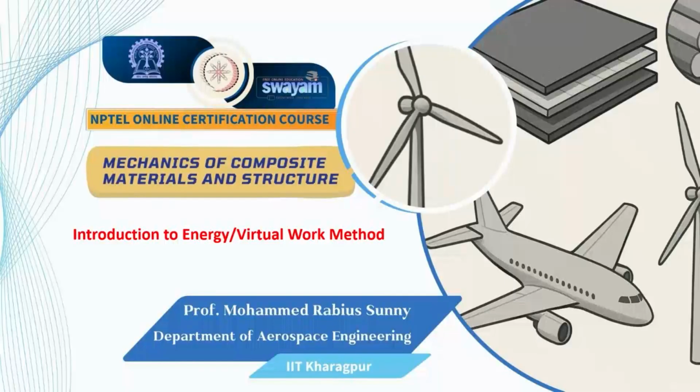Now this course mainly deals with the mechanics of composites. First we will formulate the mechanics of the composite plies and then laminates, and then we will do analysis of these laminates. So these will be mostly laminated plates. Now this analysis mainly involves solving some differential equations. Every laminate will have its own governing differential equation and set of boundary conditions, and we have to solve it. By doing that we can find out the displacement, strain and stresses in the laminates.